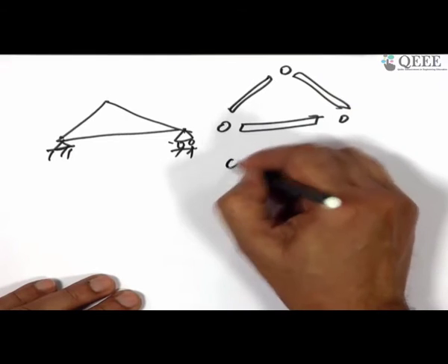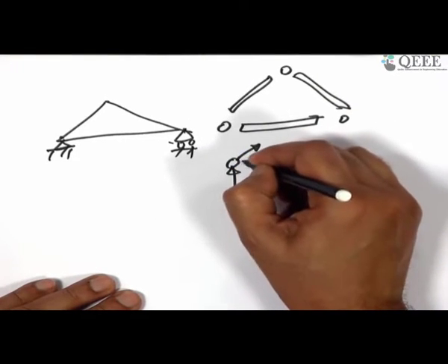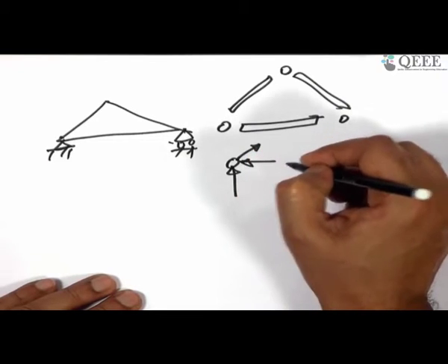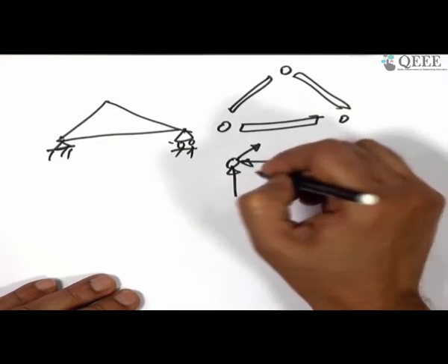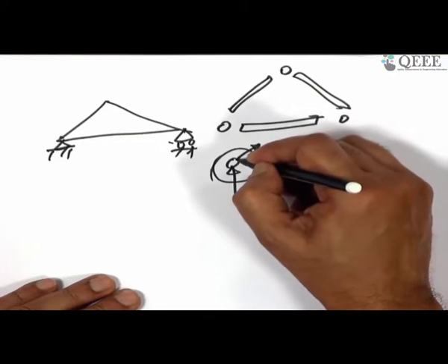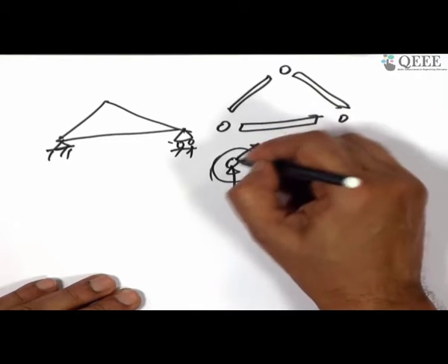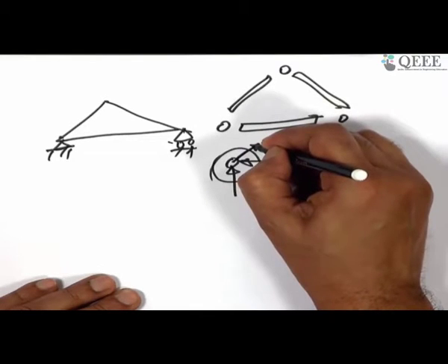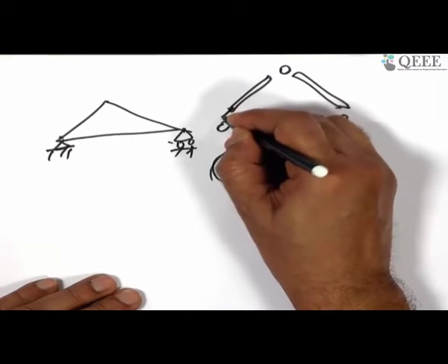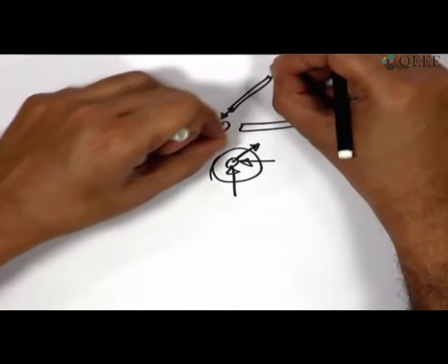You actually solve the pins, not the members really. So, you solve for the members indirectly through the equilibrium of the pins, and a force which is away from the pin is taken as tension, because if this is the direction of the force away from the pin, equal and opposite forces act on the member, and you can imagine this is trying to stretch the member.